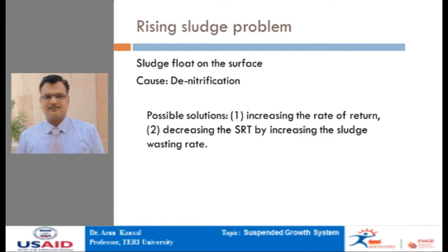Now, here in the secondary settling tank, which has a detention time somewhere around 1.5 to 2 hours, what is happening is that the sludge, which consists of highly active microorganisms, this activated biomass, goes to the bottom of the tank, and here we generally have no oxygen available. So, in case the wastewater is nitrified, the moment it enters